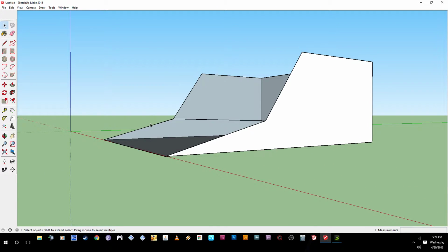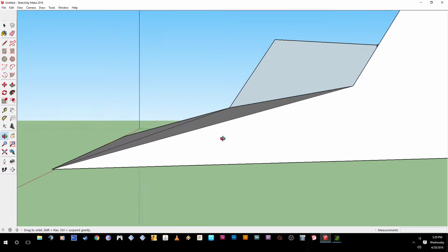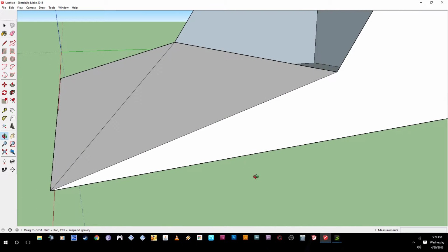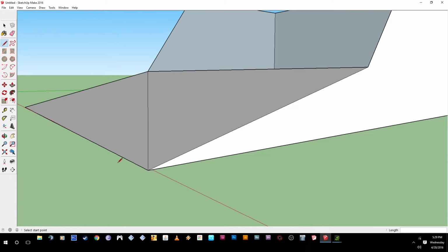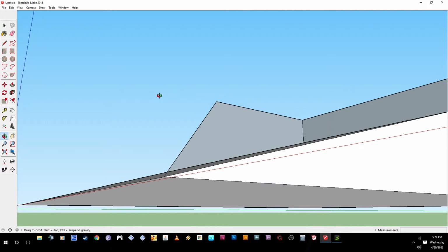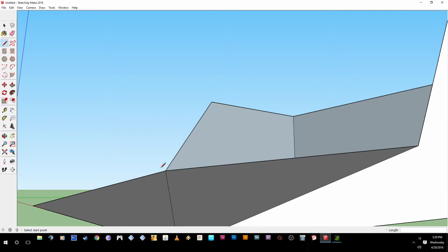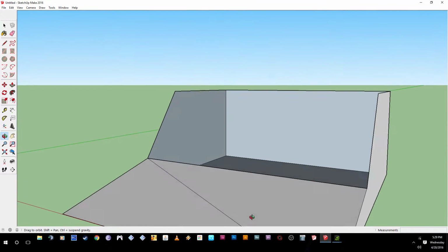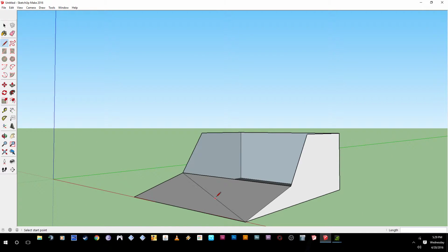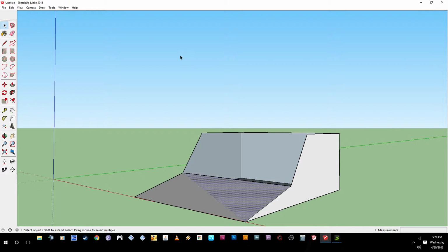Uh-oh, we have a problem. We have an elevation problem. It'll only fill in a flat portion. So why didn't it do it? Where's our offset? Weird. Probably because this isn't exactly square, okay? This is probably bending down a tiny bit that we can't even see, but it's probably got a very slight V shape going on. That's totally okay. We're going to leave it alone because we could do something to this line to make it completely disappear. Select it, soften, or hide, doesn't matter, one of those two. Whoops, just opened up a window I didn't want. Okay, back to it.